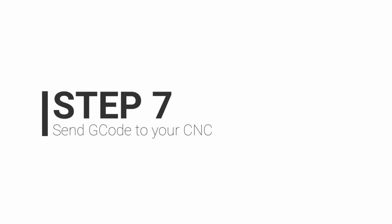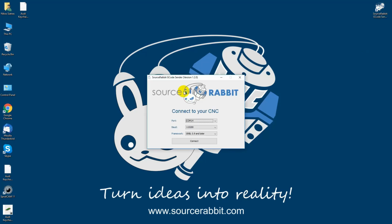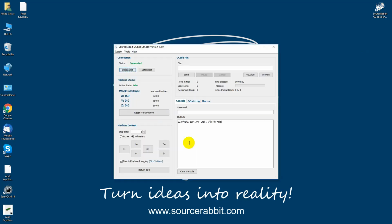Step 7. Send G-code to your CNC. With the G-code saved in your computer, it's now time to start the SourceRabbit G-code sender and send it to your CNC. Double-click the SourceRabbit G-code sender icon. Select the appropriate communication port and then click the Connect button. Now you are connected to your CNC.